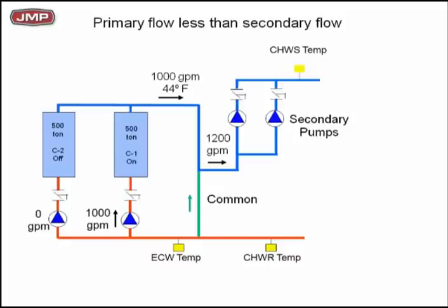Wow, interesting, huh? You telling me I'm going to take out more water than I'm putting to the T? Yeah. Now, what does that mean to you? What have you learned? What's happening in the common pipe? That means I got 200 GPM going north, bottom to the top of the screen on common pipe. And what kind of water is that going to be? Let's just see. Let's put all the numbers. I think you understand it's going to have to be hot return water. We might have a problem here. Let's just see what happens.